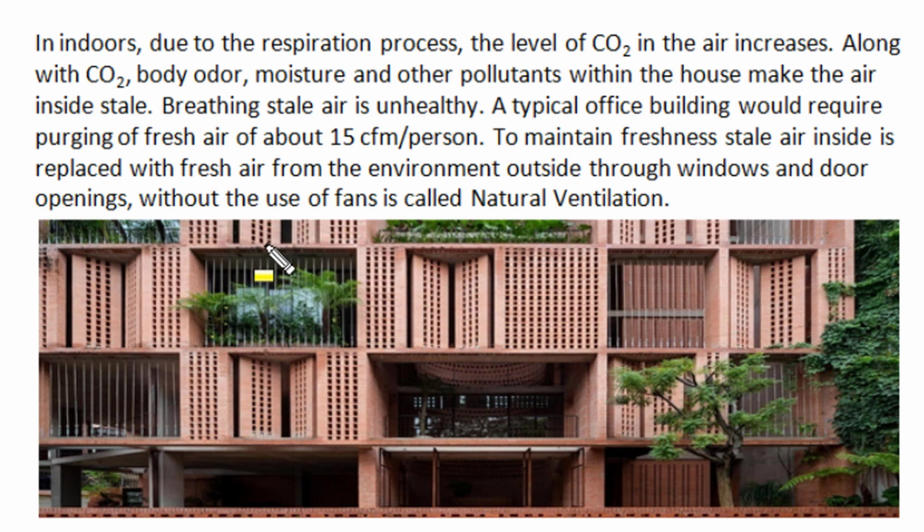To refresh stale air for healthy breathing condition in indoor positions, a typical office space would require purging or suction of fresh air of about 15 cubic feet per minute per person. And to maintain freshness in internal space, the stale air inside is replaced with fresh air from the external environment through window, door opening and other openings.